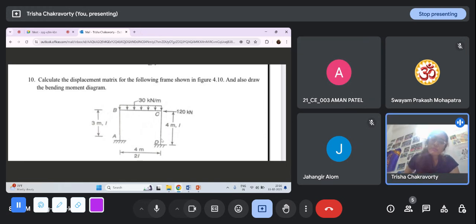नहीं नहीं, D पे मोमेंट, suppose मेरा 10 आ रहा है और C पे suppose 5 आ रहा है, in the same sense. Suppose D पे आ रहा है clockwise 10, C पे आ रहा है clockwise 5, तो फिर स्ट्रेट लाइन से ज्वाइन करना है। यहाँ पे मुझे एक 10, या इसको एक एक्सिस मानो, यहाँ पे एक 10 पॉइंट ड्रॉ करो, यहाँ पे एक 5 करो और ऐसे एक स्ट्रेट लाइन से ज्वाइन करना है, like this।